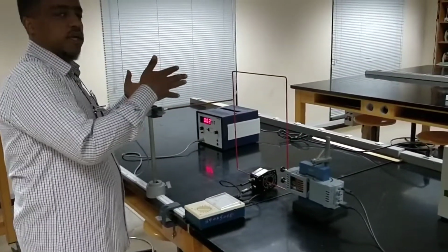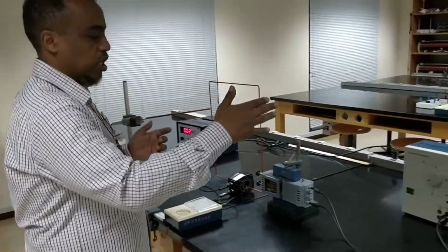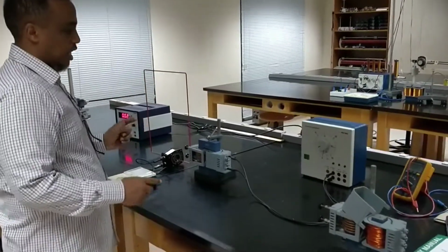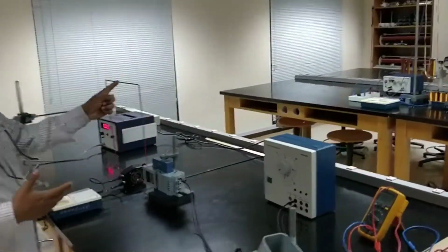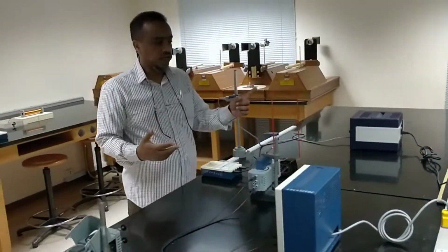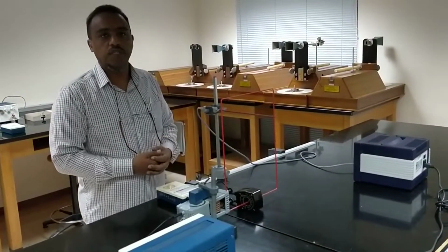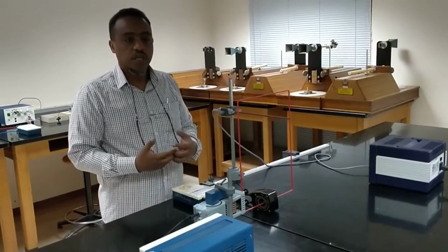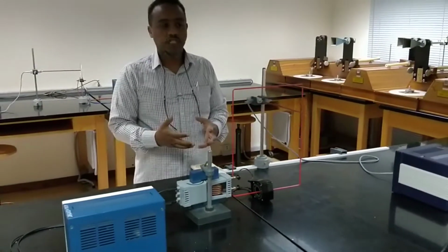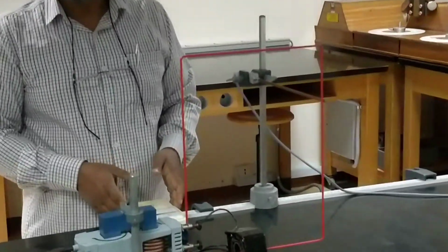Now before measuring the magnetic field, we need to measure the amount of the current here, or we need to make a relation between the current that is here compared to the current that is in here. The easiest way is to measure this current, but if we try to measure the current right away from here, it will be very difficult because the amount of current passing is very huge. 100 ampere is not safe to work with, and any mistakes we make can create a lot of problems. Just to protect ourselves, we will not try to measure it directly as we usually use an ammeter to do it.